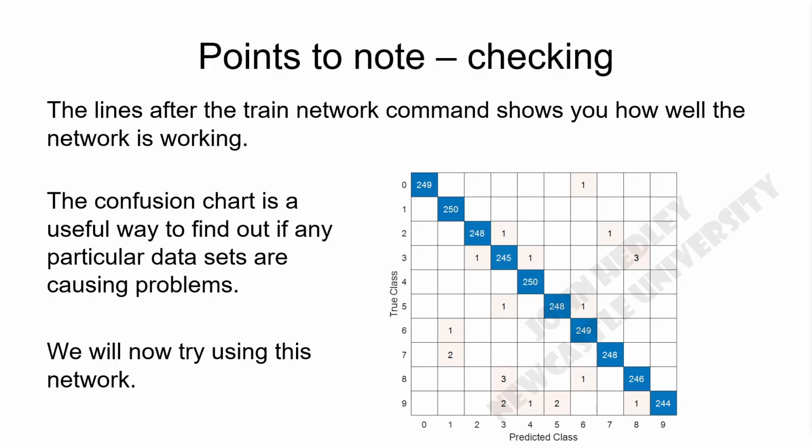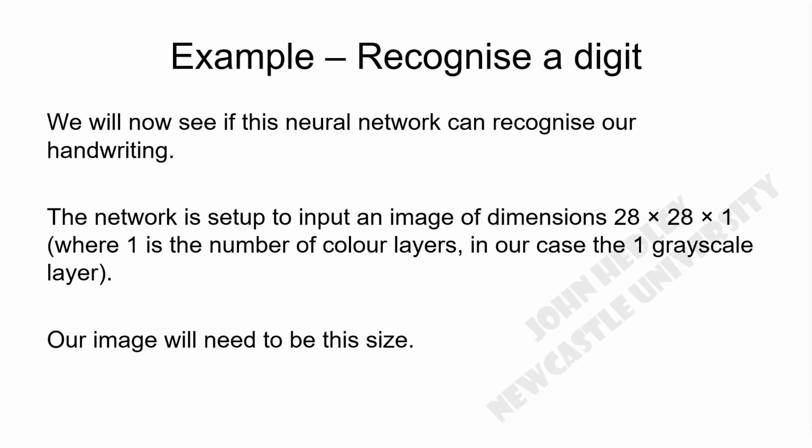Now it is trained and verified, we want to use this for our application of recognizing written digits. Let us see if it can recognize my handwriting. The input image size needs to be 28 by 28 by 1. We will create an image of this size. Note that we could create a larger image, and then use the MATLAB image resizing command to scale down this image.